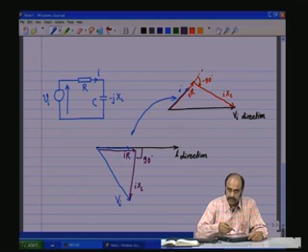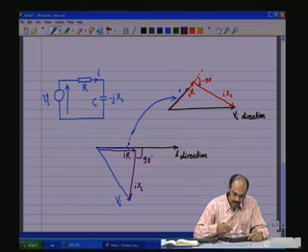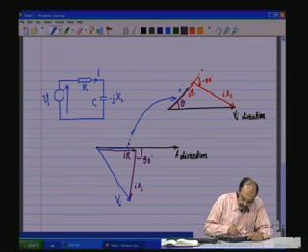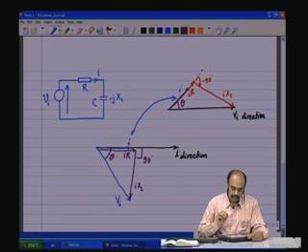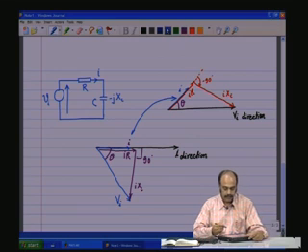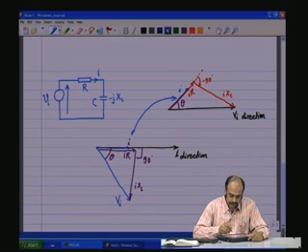See that these two are similar vector diagrams or phasor diagrams, only that here the VI vector direction was chosen as the reference, whereas here the current vector or the I vector has been chosen as the reference. However, the relative phase shift between these two is still maintained. Relative phase shift between this and this is still theta. Now, here, what is the angle theta?